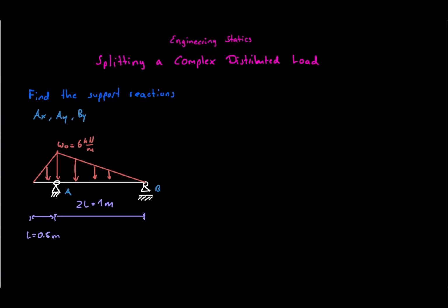Today we solve a beam carrying a distributed load that looks much more complicated than the ones we have seen before. At first glance, many students think they need a new formula, but the trick is to recognize that this load can be split into two simple triangular loads. Once we do that, everything becomes familiar.